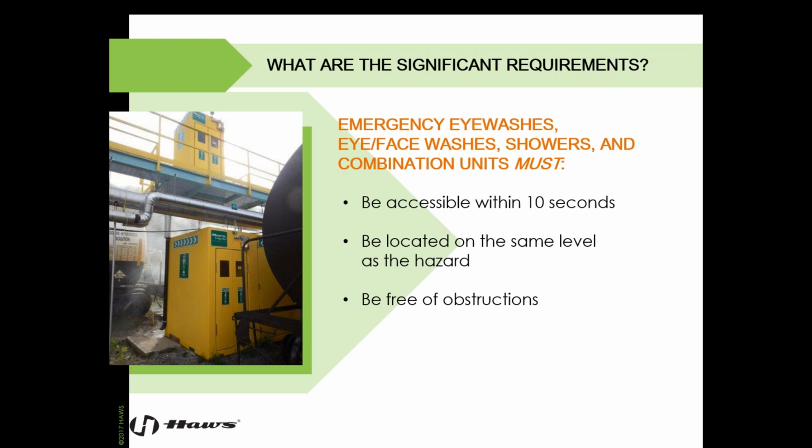So all equipment, again, all eye washes, eye face washes, showers, and combination units need to be accessible within 10 seconds. One of the most difficult parts of the standard with installation is the location aspect. It makes it hard for us as the manufacturer to recommend how many and where these pieces of equipment need to be installed because we don't know the potential hazards at your facilities. So the 10-second rule tends to fall on the owner or the installer. I'd recommend utilizing your health and safety manager or team to evaluate the workplace so you can determine quantity and